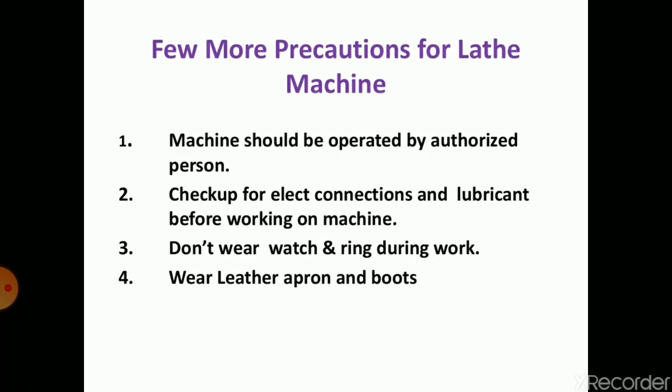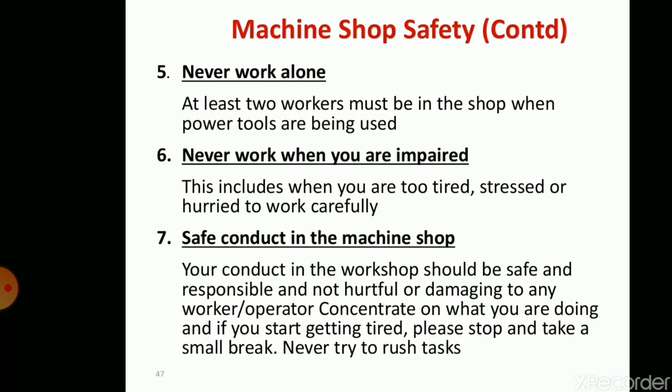Few more precautions for these machines are: machines should be operated by authorized person. Check up for electrical connections and lubricant before working on machine. Don't wear watch and ring during work. Very important precaution. Wear leather apron and boots.